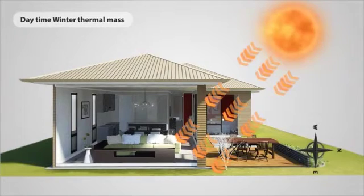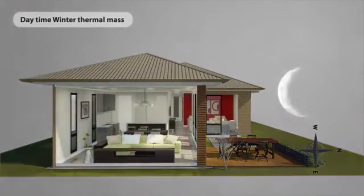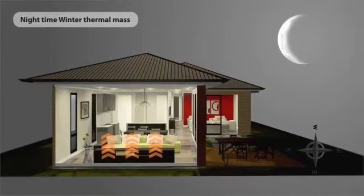The winter sun shines down into the living rooms. The heat is stored in the thermal mass. As the air inside the house cools during the night, the heat in the thermal mass gets re-released back into the room and helps to maintain the internal temperature, requiring less heating.